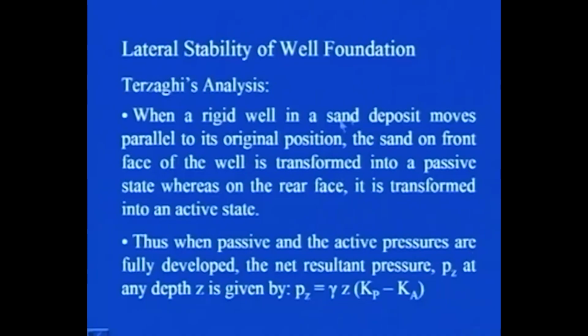In this one it has been considered that when a rigid well in a sand deposit moves parallel to its original position, the sand on the front face of the well is transformed into a passive state, whereas the sand on the rear face is transformed into an active state.